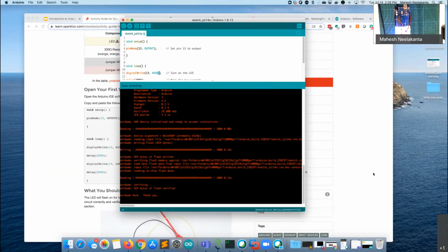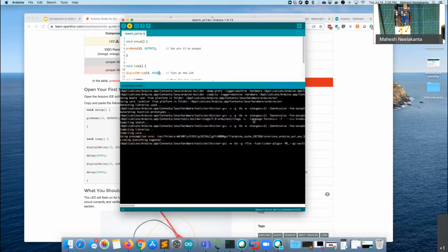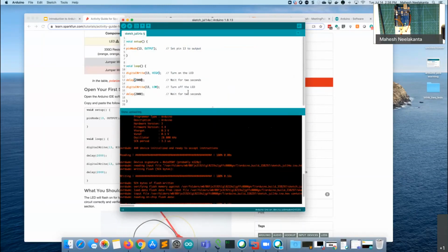And if you look carefully, while I was uploading it, I'm going to do it again. Have a look at my video. You'll see the blue light blink really fast. And do it again. And cancel. Watch very carefully. There. If you saw it, it blinked really fast. That's when it was actually uploading the code. And so this is turning on and off every 2000 milliseconds or 2 seconds.